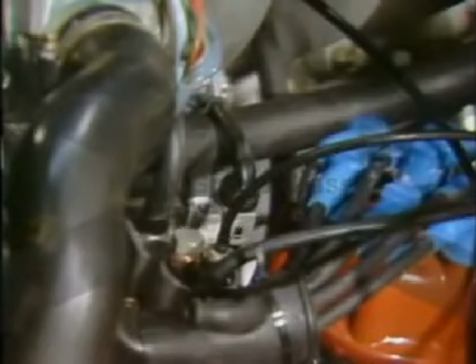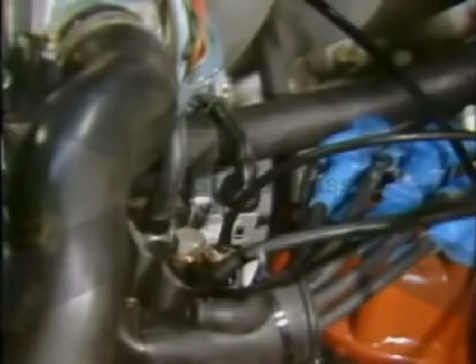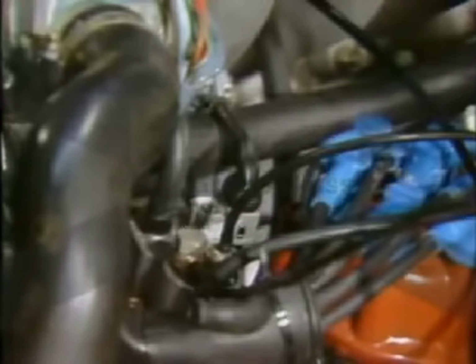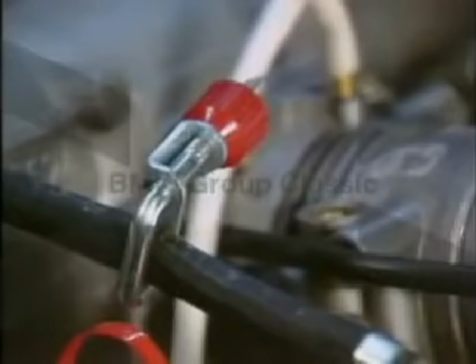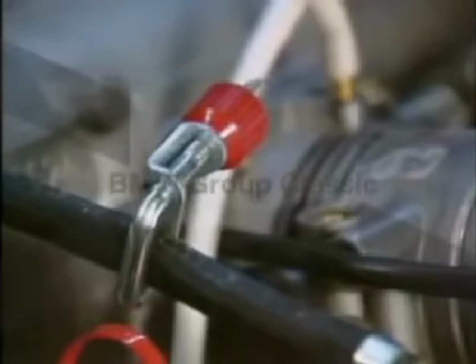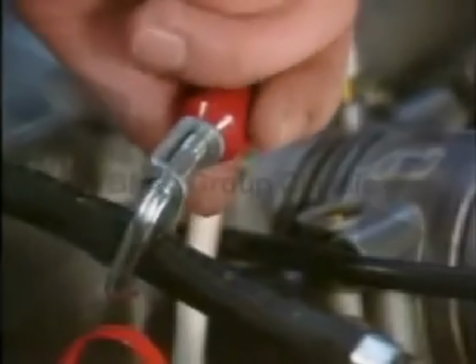The actual control pressure value is dependent upon temperature. We therefore measure the temperature of the warm-up regulator. We do this using the service tester temperature probe. Now we can test. We open the clamp and switch on the ignition.